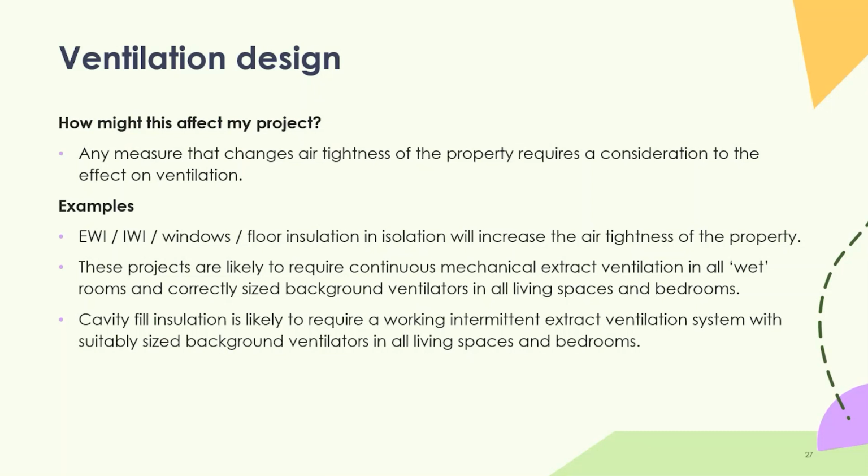So when you do that, as I mentioned, you're very likely to require some kind of continuous mechanical extract ventilation in the wet rooms and some sort of background ventilators, correctly sized. And they can be a vent in the wall, or commonly they're trickle vents in windows, so a little sort of slot at the top of the windows with a small sort of plastic controller that can be moved across.